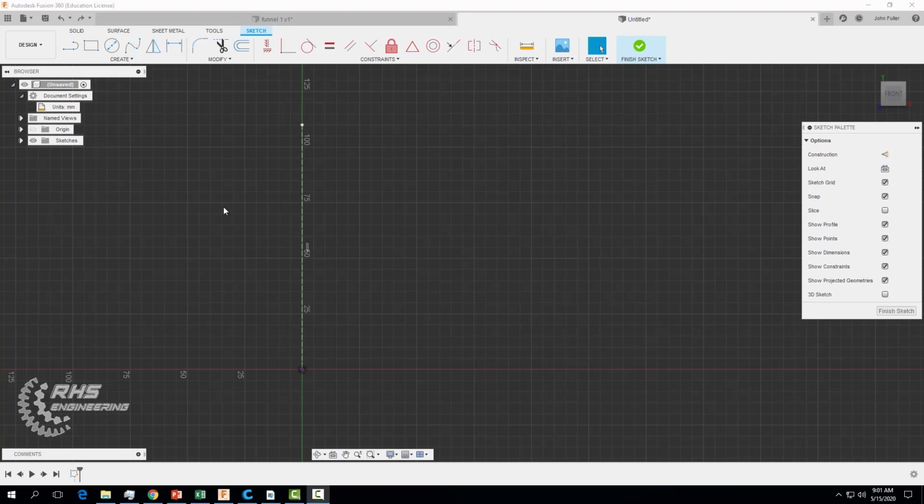Now imagine, if you can, a funnel that you sliced right down the middle. That exposed face that you just cut represents the 2D profile sketch we're going to draw now. Once we draw that 2D profile, we're then going to revolve it around our center axis here. All right, so now let's go ahead and start drawing out the 2D profile.